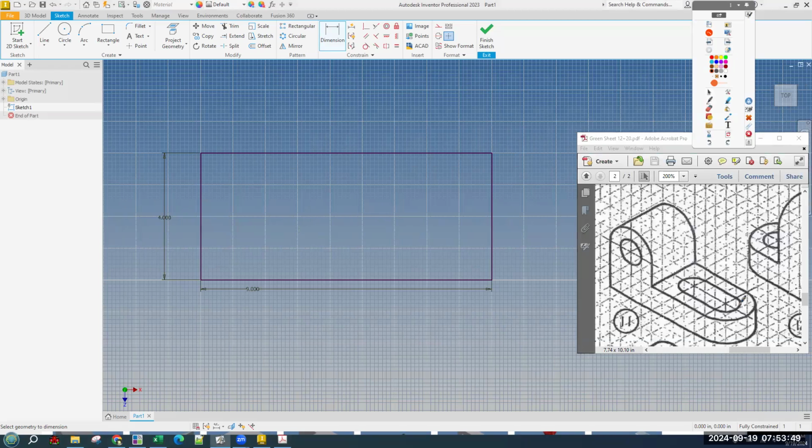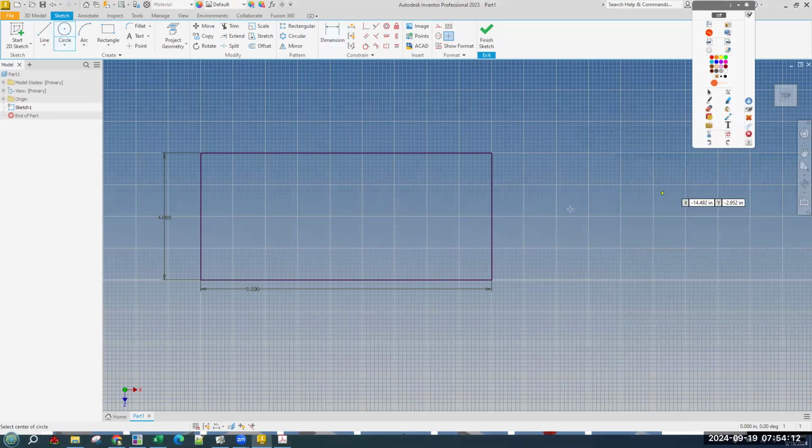And we know that this curved part lines up perfectly with the edges, because you can see this little faint mark, the center mark points straight out. And because those intersections are the same, we can infer that this is a perfect semicircle. And we don't even need to dimension it. If we get a circle tool, first snap is the exact center point where it turns to green, first click, and second click is in the corner.